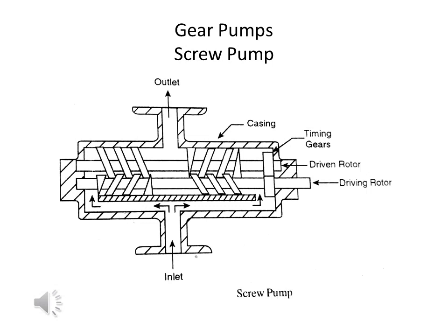Now when the motor starts to rotate, the driving gear and the driven gear will be moving away from each other. When both the helical gears are moving away from each other, suction will be created on both sides. See the direction of the oil: because of the suction created in between the driving and driven rotor, the oil gets in,